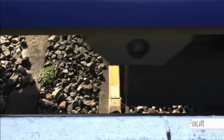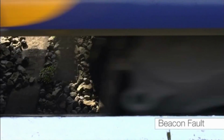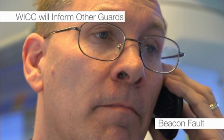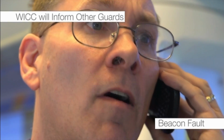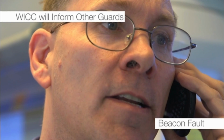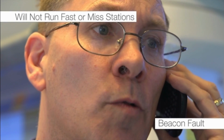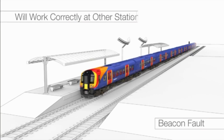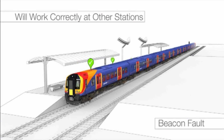If a beacon fault has presented itself, Wessex Integrated Control Centre, or WICC, should be contacted as soon as possible. Patrol, I believe that there is a fault with the beacon at station 5. That's right, I had to ask the driver to carry out an override at the station. WICC will inform other guards with a BlackBerry message detailing the beacon fault. A train of 12 carriages will not run fast or miss stations because of a beacon fault.